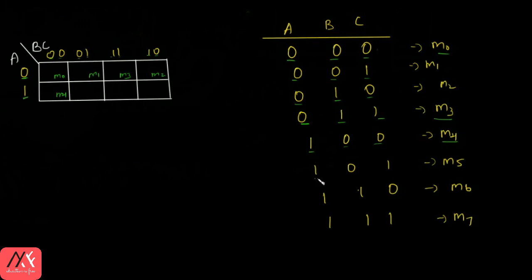So once you finish doing this, you'll be very comfortable in solving problems, right? If you fill the K map with the proper min terms, then half of the problem will be solved, right? So you'll be very confident in solving problems. In the next video, we'll be solving problems actually. In this video, I have shown you how to form groups and how to write the min terms. So these are nothing but min terms. The same with max terms also.